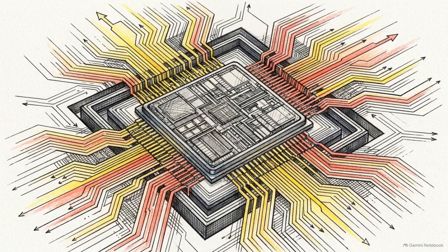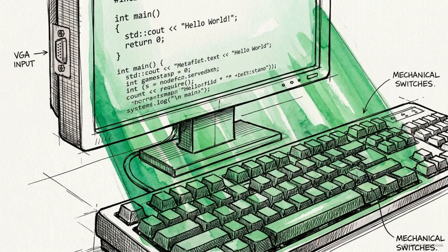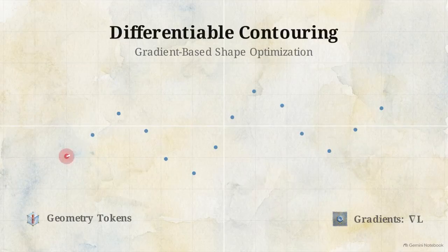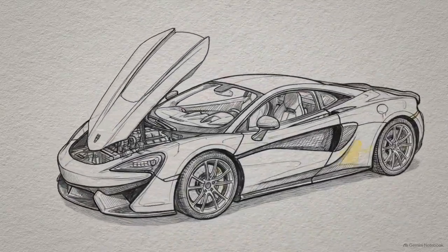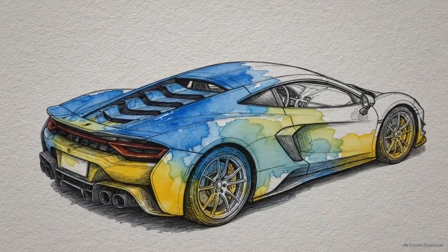The processing methodology here is entirely local and highly parallelizable. Because it skips rendering optimization, the CUDA execution scales effectively to massive resolutions without proportionate computational drag. The implementation does currently rely heavily on specific CUDA environments and C++ compilers. Additionally, researchers note that extreme, non-standard geometric topologies will require further testing to guarantee absolute robustness. The immediate next step for this framework is differentiable contouring. Integrating these tokens natively into gradient-based learning pipelines will allow massive diffusion models to directly generate explicit, high-fidelity 3D geometry.